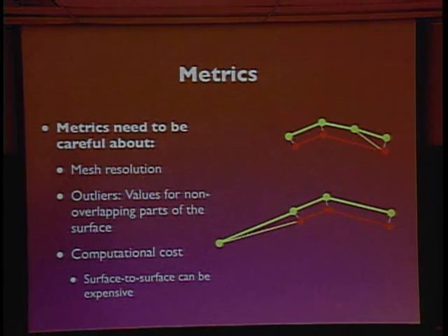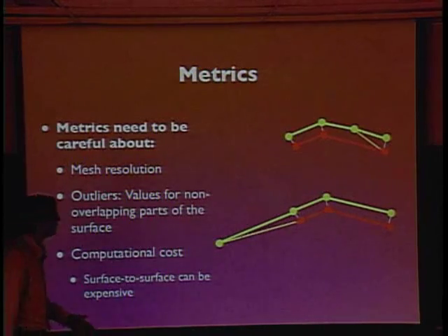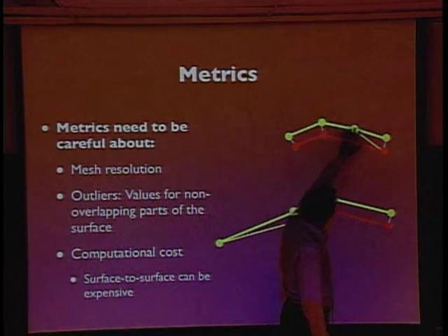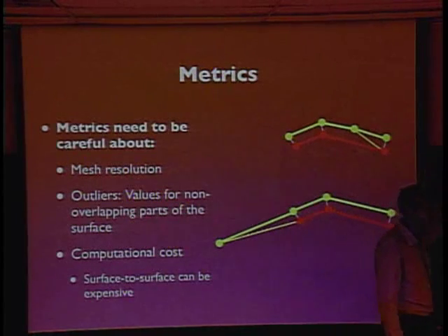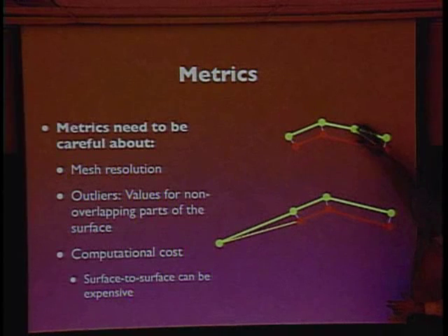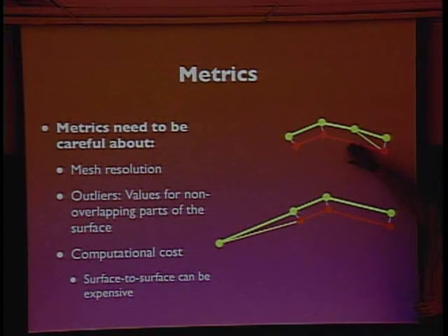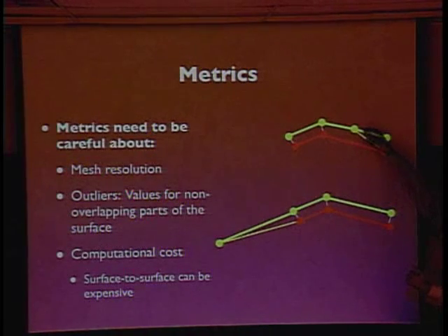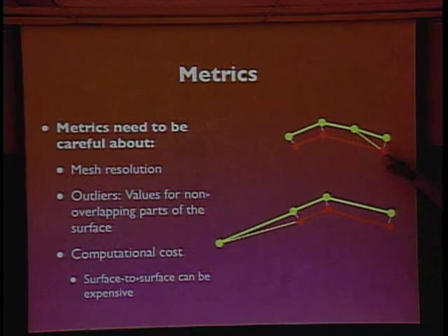We'll talk about mesh simplification later, but it's very often the case that if you have a planar surface, something that's more or less flat on your object, and you scan it twice, sometimes you can get a point that's right in the middle, and maybe sometimes you won't. And yet, what I've told you, at least for some of the techniques, is that for each point, you have it contribute its opinion to how close the other surface is. So for this one, the fit seems pretty bad because its closest point on the other surface is way over here, when in reality it's actually not that far away at all. So that's one reason to use a point-to-surface or a point-to-plane distance as opposed to a point-to-point distance.